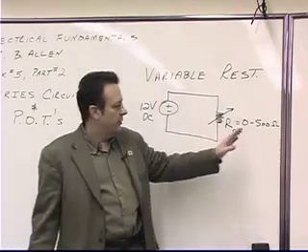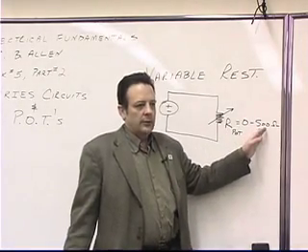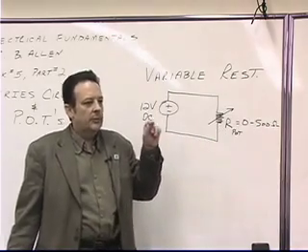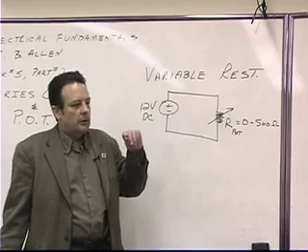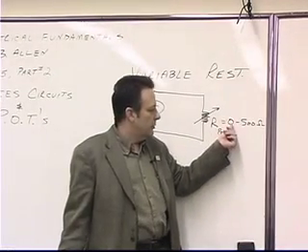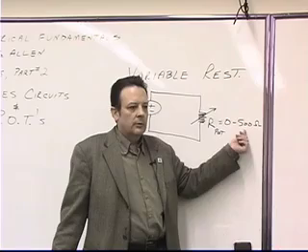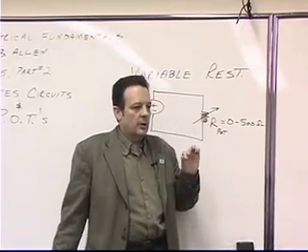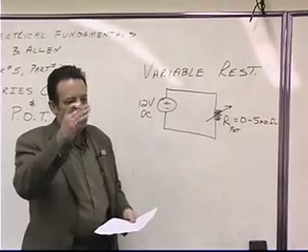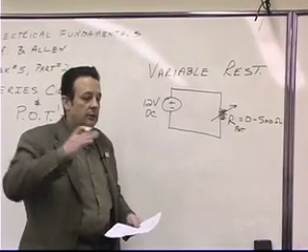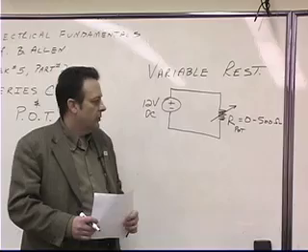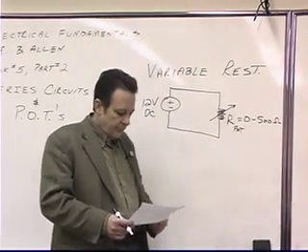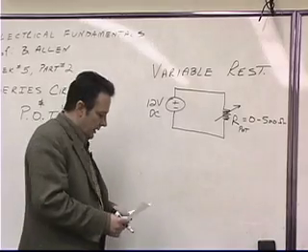In other words, if this is 50 million, then it's going to be difficult for you to get changes of 10 ohms each time that you turn the knob. Whereas if this goes from 0 to 100 ohms, then you're going to be able to affect changes of 10 ohms by turning the knob. Okay? In other words, the jump in increase or decrease of resistance is going to be affected by the range. Right? 0 always indicating a short.